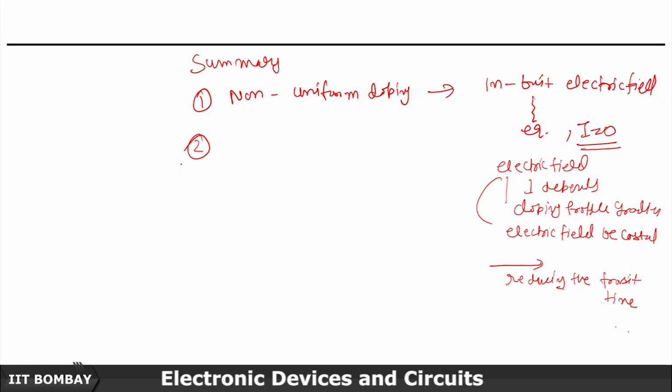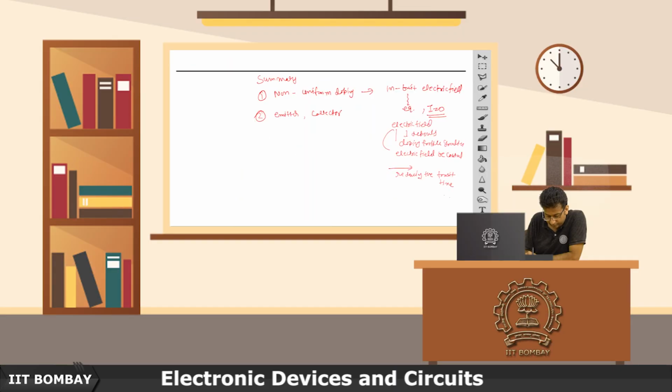So that's a very important advantage of this non-uniform doping. Then we talked about different configurations, common base, common emitter and common collector. And afterwards we talked about narrow base width, which explains why the IC versus VCE curves are not linear, right.